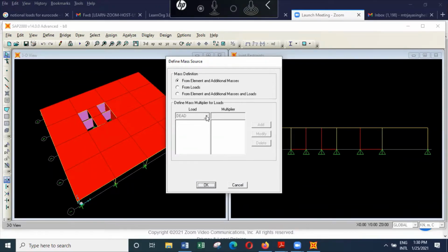go there and go to this one and say dead weight is always there. So that is due to the beams, columns, slabs, and shear walls that we have already defined. So we don't have to worry of anything, because dead load automatically will be calculated by the program and its multiplier is 1.